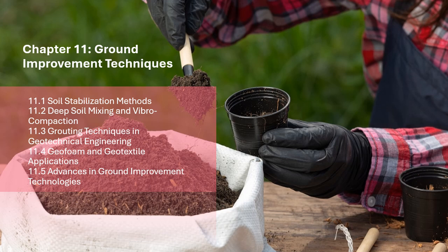1.3.1.3 Jet grouting. Jet grouting uses high-pressure grout jets to erode the soil and mix it with the grout, creating solidified soil cement columns. The technique is used to treat deep soils and is effective in both cohesive and non-cohesive soils. Jet grouting can be performed at depths ranging from shallow to very deep levels.